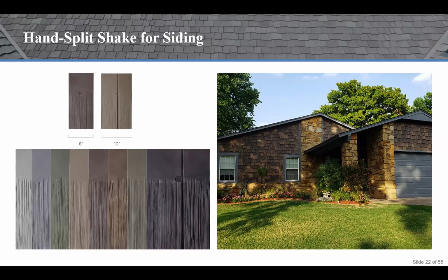These come in 8 and 10-inch widths, 18 inches tall. It also has a false keyway for that multi-width appearance. It can be installed at 6, 7, and 8-inch exposures. Low maintenance, there's no painting required. It has that thick construction, so those deep grooves really give that realistic grain pattern. It combines with dramatic shadows to give you a real visual richness. And what's great, it's resistant to fading, rotting, cracking, creepy crawly pests, all that kind of fun stuff.